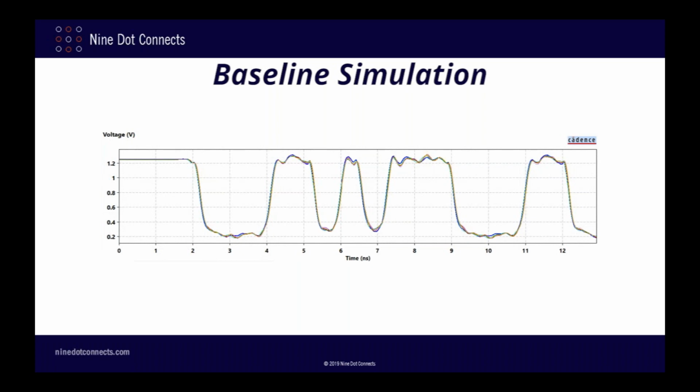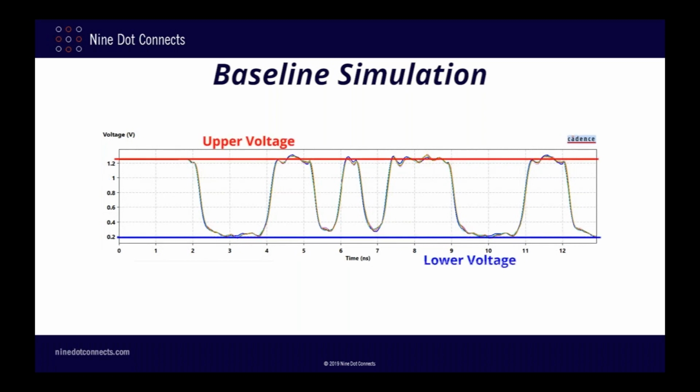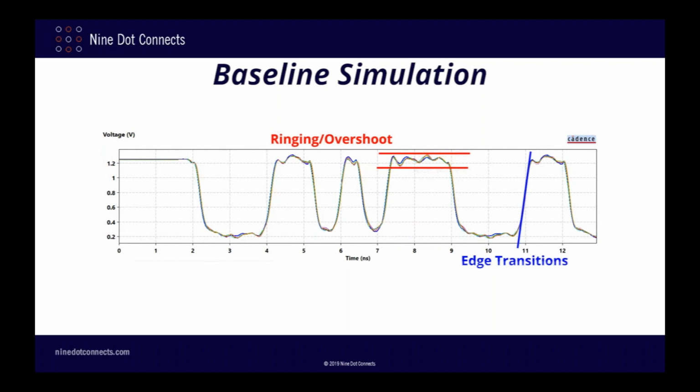As you see, it looks pretty clean, which is what I expected since I already knew this board worked in the real world. Some of the things we want to look for are the upper and lower voltage levels, ringing and overshoot, and the transitions of the signal edges.